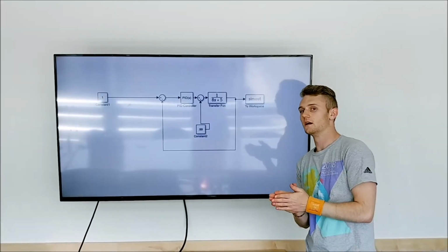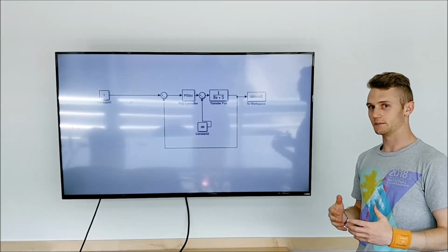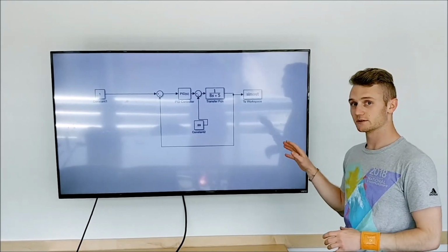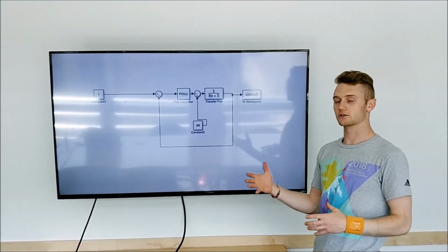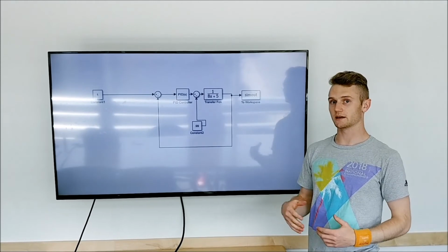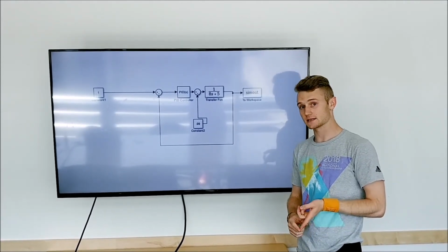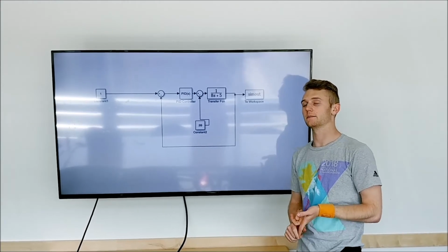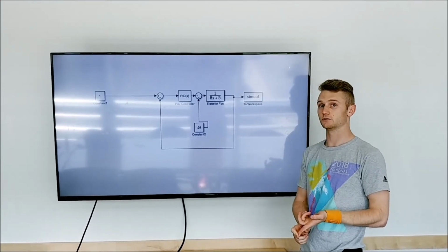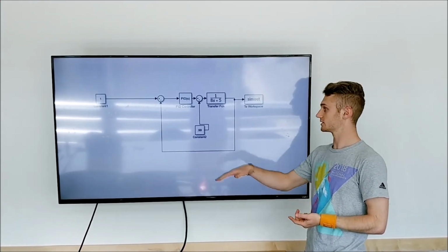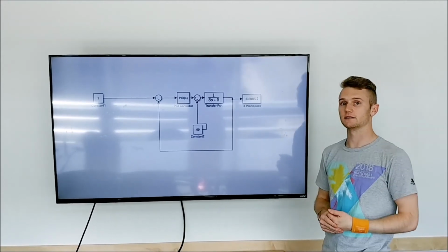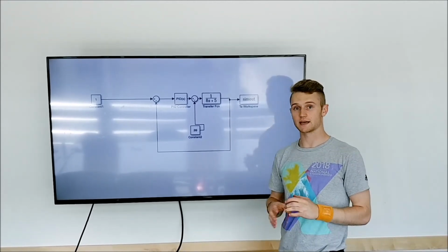Alright, so to wrap this up, we were able to meet all of our constraints and goals enumerated in the beginning of the video. That we wanted to limit the rise time to 0.1 seconds, limit the percent overshoot to 10% for the first jump, and limit the settling time to 1 second.